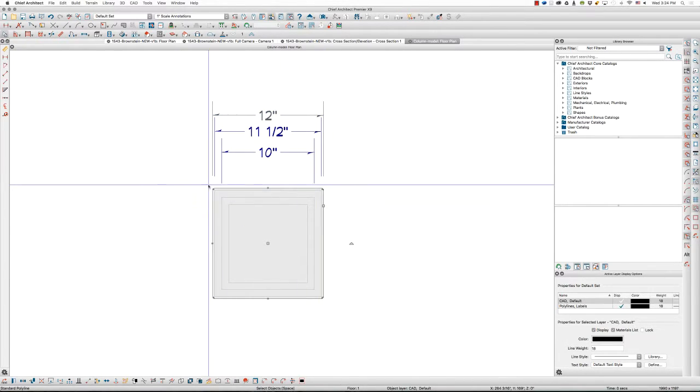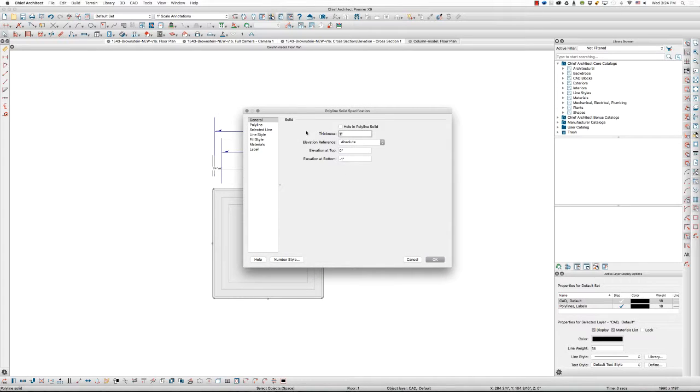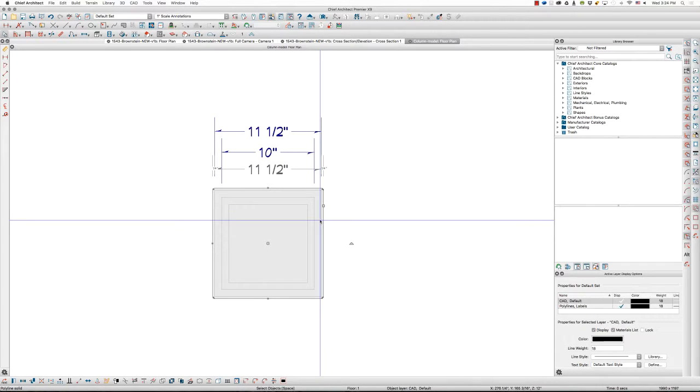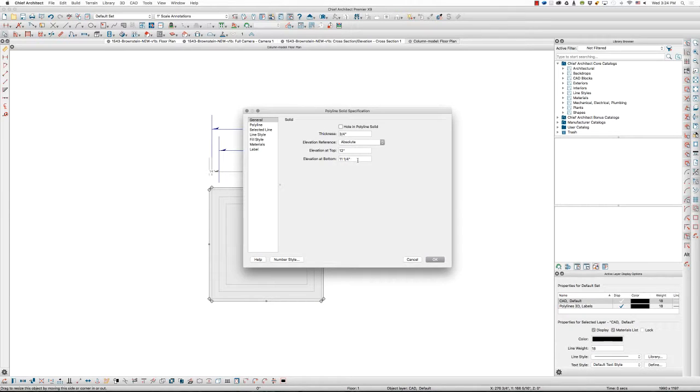This pedestal piece, I'm going to make 12 inches tall, at 12 inches off the floor. I'm going to make it 3/4 of an inch thick, and the top, I want it to be at 12 inches. The base then, so if the top's at 12, it's 3/4 of an inch thick, the bottom's at 11.25.